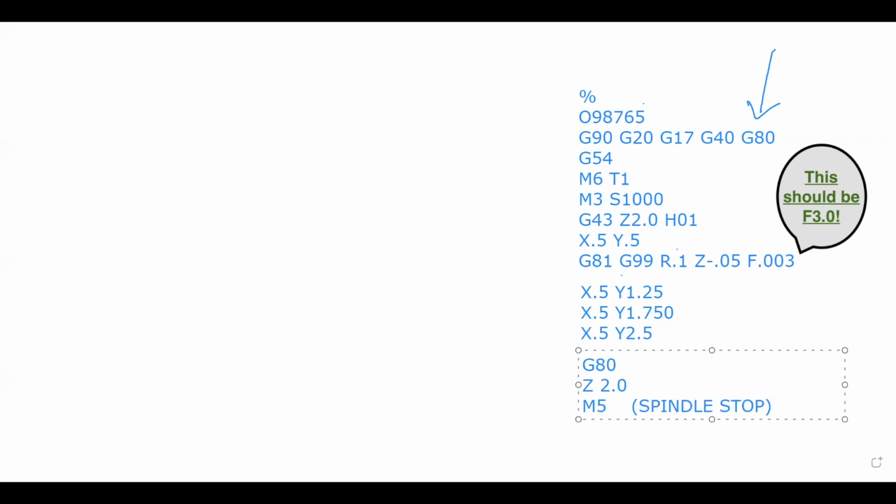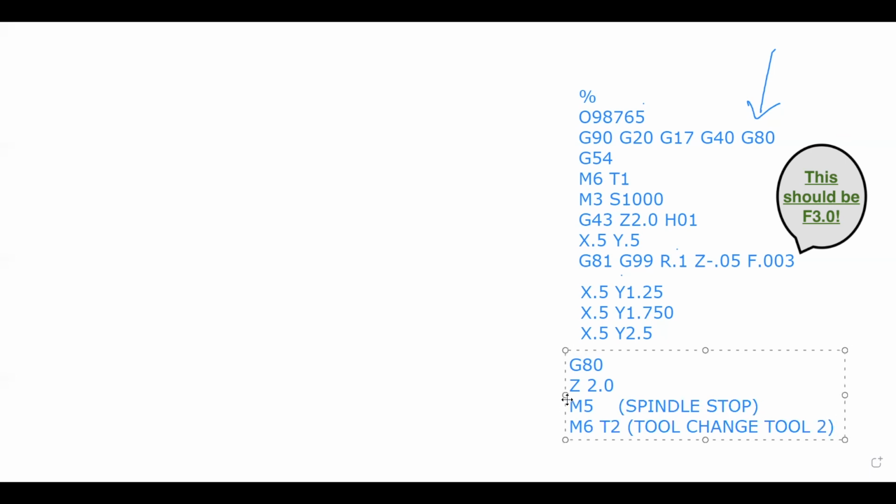And then we can call up our next tool, which would be M6 T2. Tool change, tool 2. When we do that, the machine is going to move up in the Z axis and then go to the automatic tool changer and change our tool.